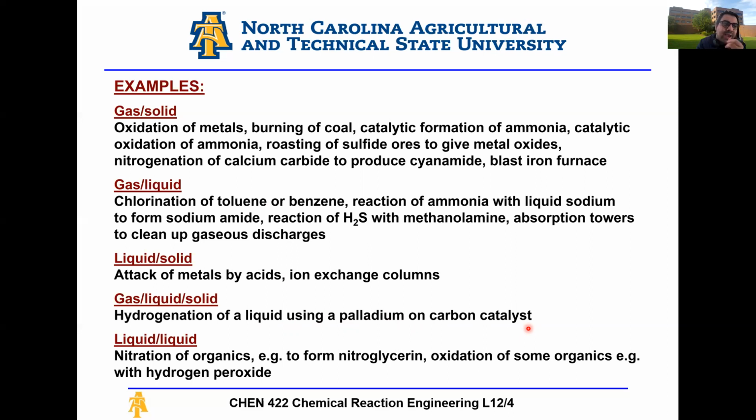Hydrogen and carbon monoxide react and they make diesel, and then I separate the diesel from my wax and my catalyst, and I recycle the catalyst back, take the diesel and sell it to the market. Liquid-liquid reactions are also possible, and these are considered multi-phase reactions because these are liquids of different densities and different miscibilities. They don't readily mix and dissolve within each other to form a homogeneous mixture, so they are considered a heterogeneous type of process. So nitration of organics to form nitroglycerin, oxidation of organics to make hydrogen peroxide. These are examples of liquid-liquid reactions. Okay.